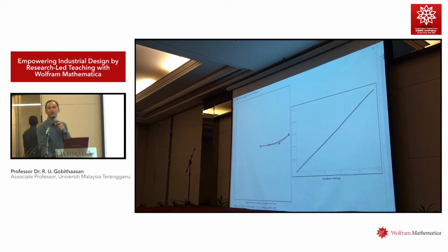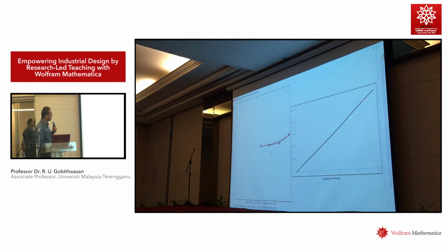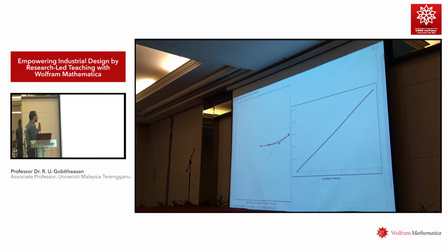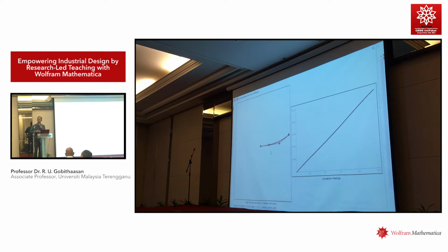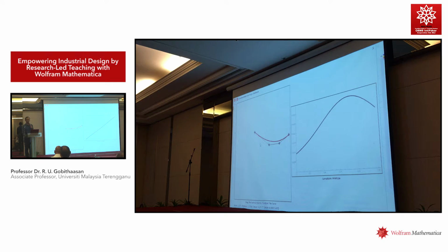This is a piece of Bezier cubic. As you can see, this side here is a curvature. The curvature is very much beautiful. It's just monotone increase. So if you use such a curve to design your object, you will get a beautiful product once you manufacture.